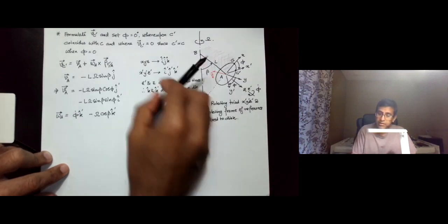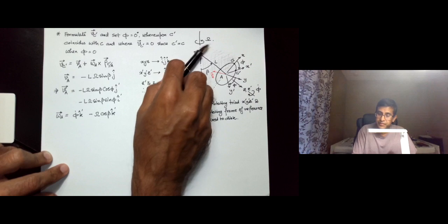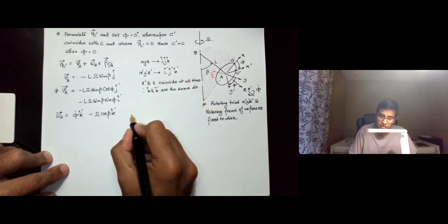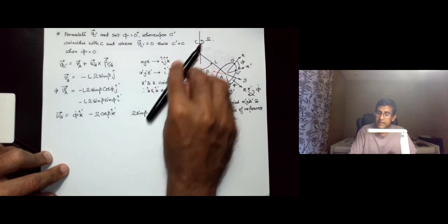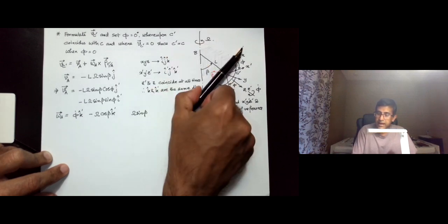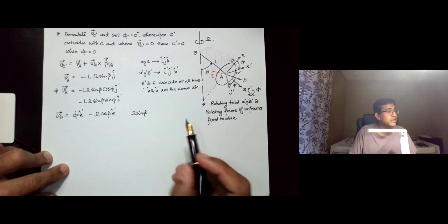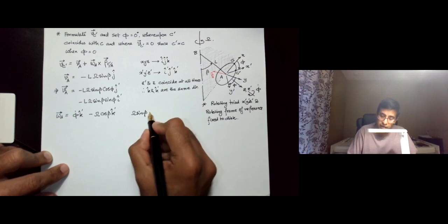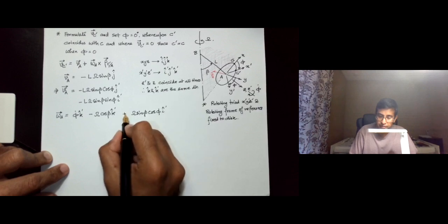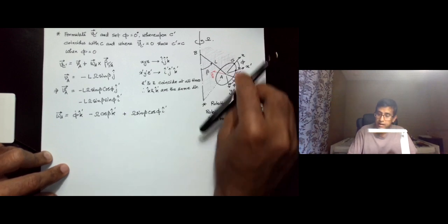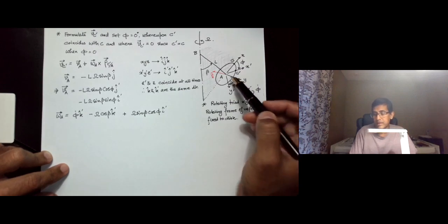The other vector is going to be produced in the x direction, which is omega sine beta, and that x direction will have a cosine phi component in the x prime direction, so cosine phi i prime, and a minus sine phi component in the j prime direction.